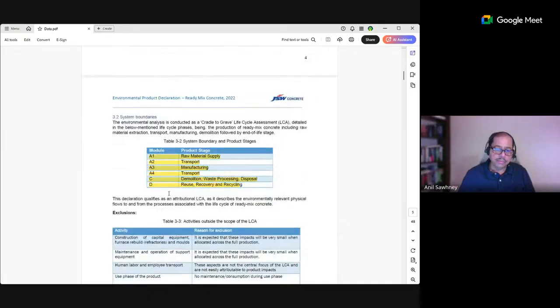The EPD, very interestingly, I have seen EPDs that only give modules A1, A2, A3. But this EPD has A4 also. And obviously, very few current EPDs give C and D module emissions also. For today's example, we are not looking at C and D. Maybe we'll look at those when we cover how the workflow and calculations work for module C and module D.